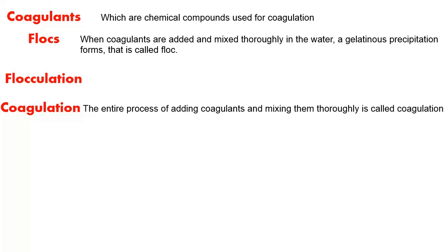When coagulation completes, we again give some detention time there, but it is much less than the sedimentation detention time. Then the water is allowed into the sedimentation tank. In the sedimentation tank, the flocs all come and settle to the bottom and they are removed.